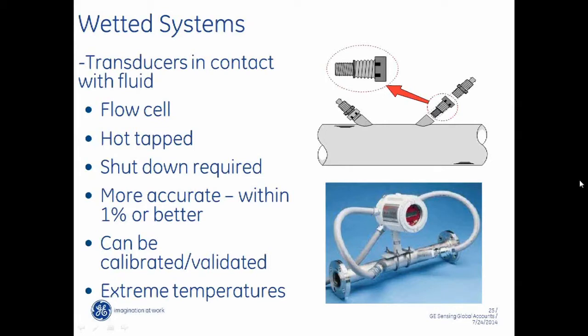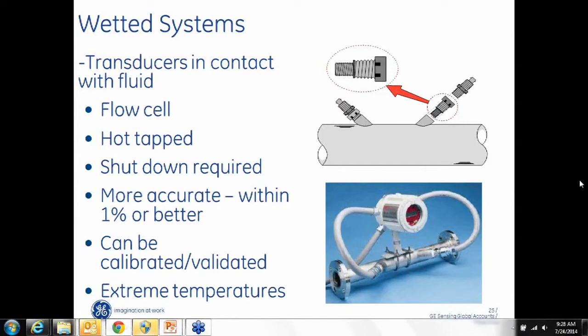And remember how I talked about having the couplant that goes between the transducer and the pipe. When you're dealing with a hot pipe like that, the couplant that we put on, and we have one that can go onto the pipe, it's not a problem, but it does smoke a little bit until it cures. It becomes kind of a rubber material. It can peel off the pipe, but during that time, there are EHS issues. You have to make sure that you've got sufficient clean air in an area where that's not going to be a bother to you or anybody else in a building. So there's that kind of consideration, but it can be done, and we have done it.